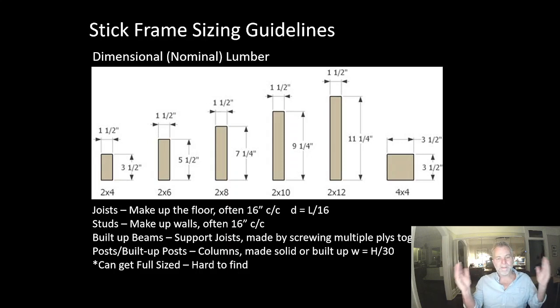The spacing of the joists is determined by what you put on the joists. So if we're putting a layer of 3/4 or 19 millimeter plywood on top of the joists, that plywood will span about 16 inches. On the roof, we're not as concerned about it feeling spongy when we walk on it, so we would push that to 24 inches or 600 millimeters.